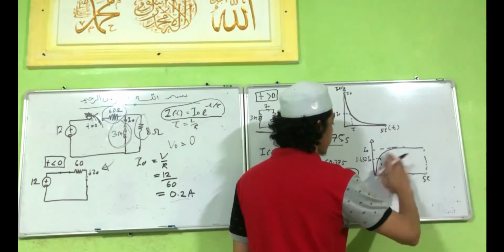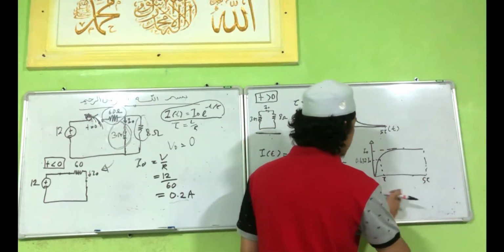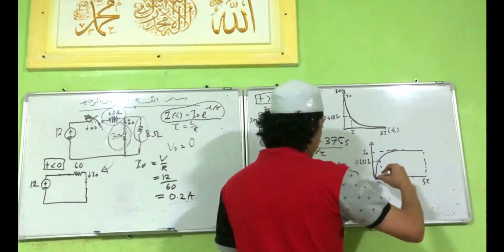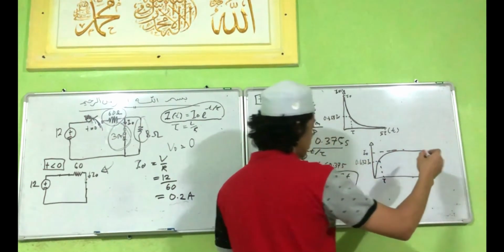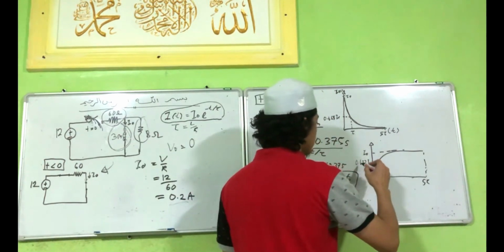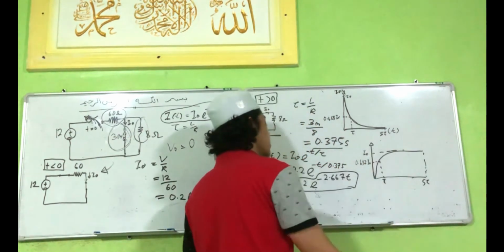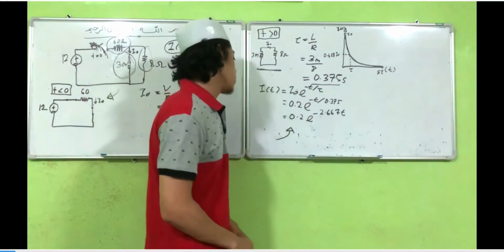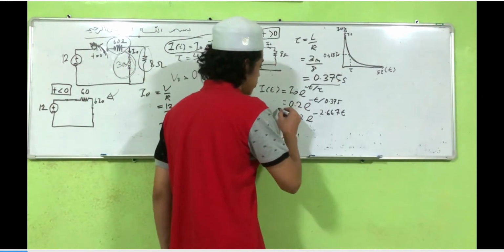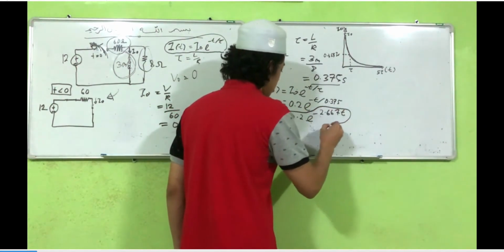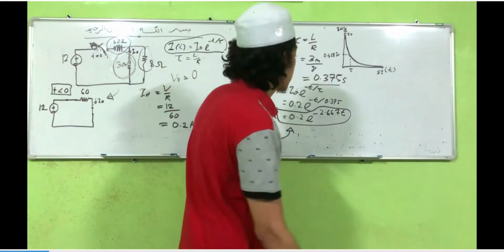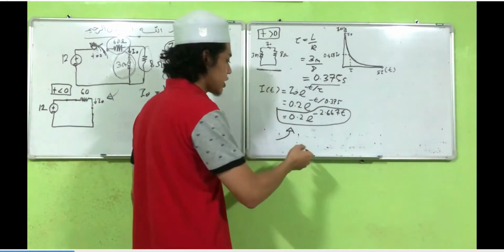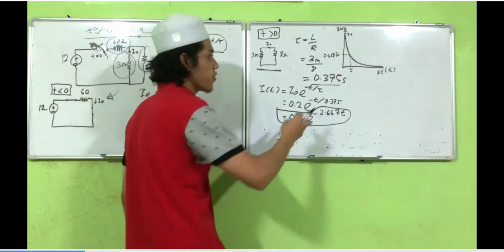After that, to get the value of charging of the RL circuit, as we know, the full length of this waveform is 5 tau. So the value at one tau in charging is 0.632 multiplied by I naught. So we have found the value of initial current, this one. This value of initial current is in a discharging waveform, discharging waveform like this.